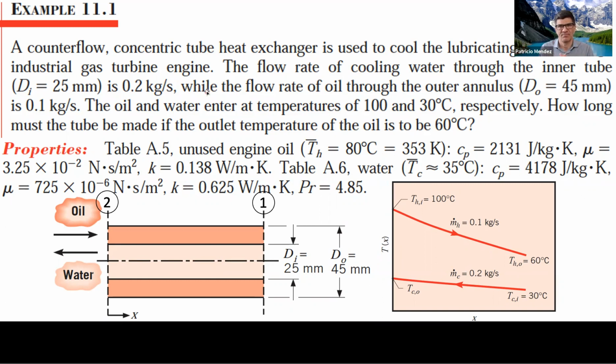You'll have to use both. Here we worry only about heat transfer, and we take these flows related to pressure losses as given by the god of fluid dynamics that is in another church right now. So here we have the flow of water, in addition to the flow of oil. And we have the diameter of the inner cylinder and the diameter of the outer cylinder. The oil comes in at 100 degrees and the water comes in at 30 degrees.